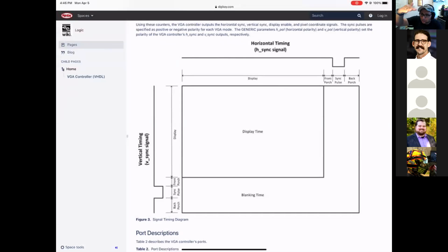So we take it horizontal, horizontal, horizontal, horizontal. When we're done with horizontal, we take the second vertical and move forward. Then you do the third one, horizontal, horizontal, horizontal. Then you make another vertical. Then we return to scan all the horizontal lines and so on until you end up, and then you start from scratch. All of this happens in the background of the VGA.